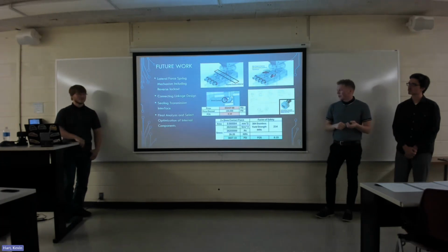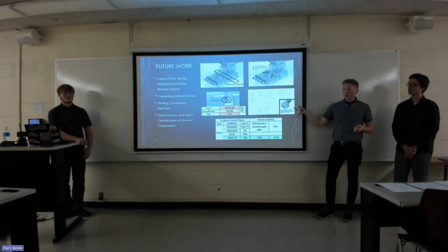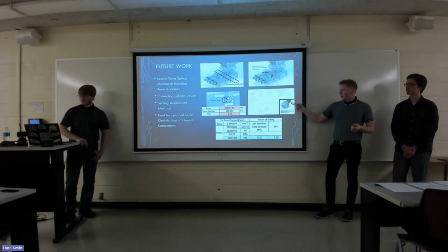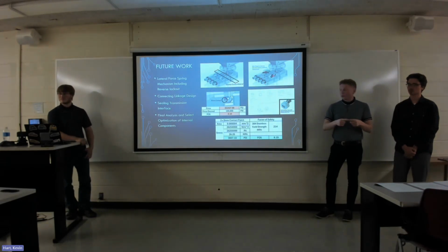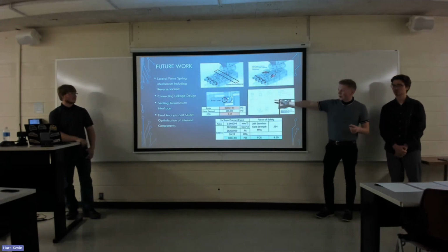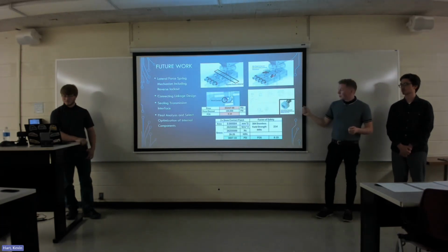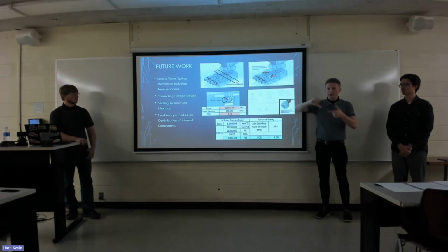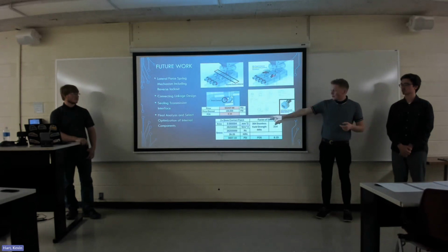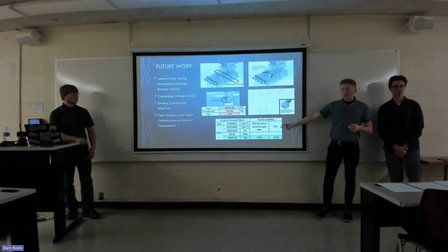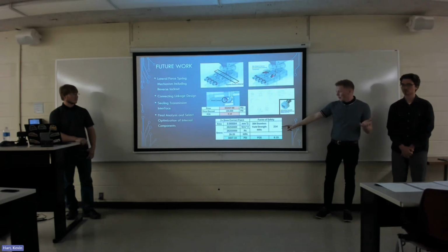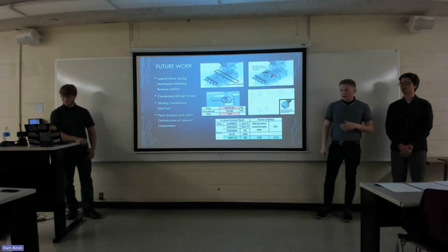And so we leaned back on our research, and on the A80 Supra, they use a plastic bushing on the end of the spherical output rod that makes their point contact cylindrical contact on their selection rod. But we couldn't do that since the height of our spherical ball changes based on gear position. So we are going to use the pivot from this, as well as have a rectangular contact patch on here at a size of 2 mm by 2 mm, which will result in just a normal contact, giving us 3,800 psi of pressure and a factor of safety of 8.2.